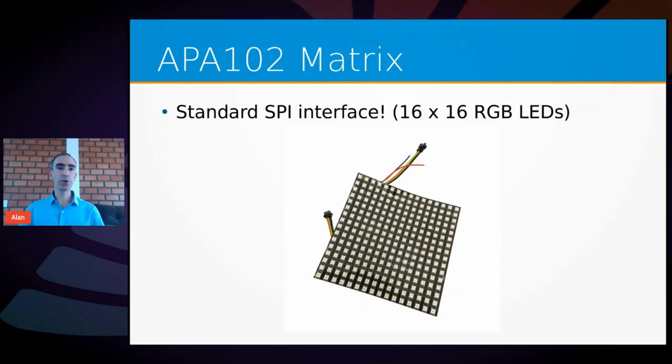Just out of curiosity, the other low-cost RGB LED, the WS2812, is also supported on NuttX, but I don't like using this kind of timing to control the device. I prefer to use a standard interface like SPI.